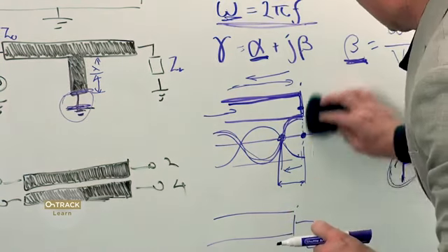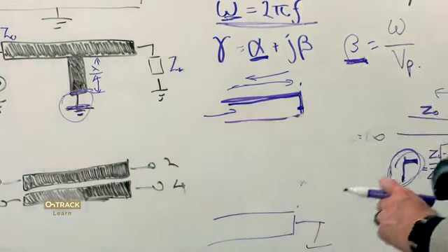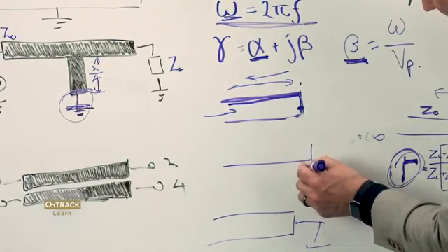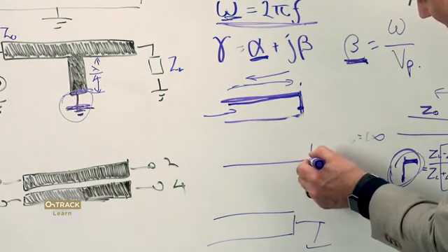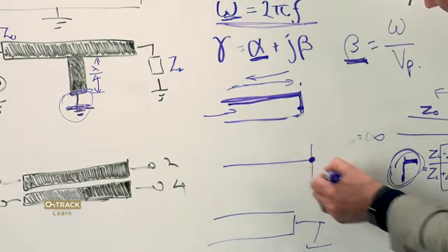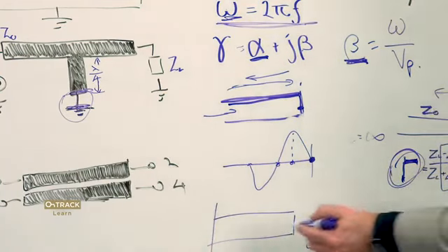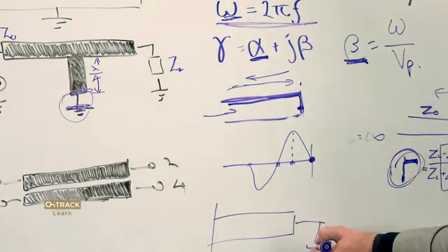Okay, so if that's fixed at ground for a quarter wave stub that's terminated to a short, what do we have? Let's redraw that little waveform there. All the energy is reflected, but reflected in reverse. It's negative. And the voltage of the standing wave is fixed at 0. And so then we have at a quarter wave a peak. And so a quarter wavelength stub shorted at one end appears like an open circuit.